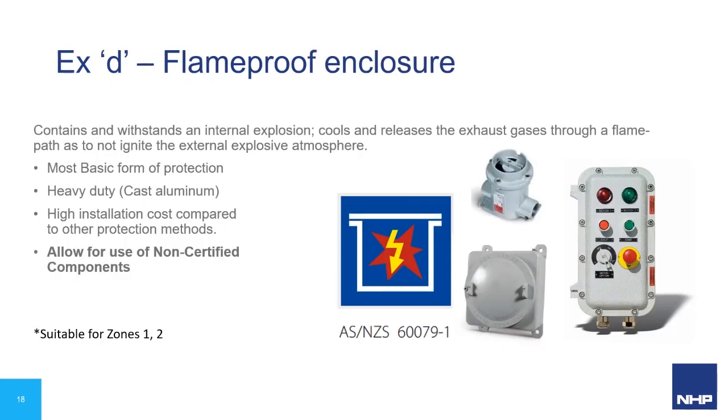Now, EXD is a flameproof enclosure, so you don't want to confuse this with fire-rated enclosures, as they are two completely different things. A flameproof enclosure is allowed to breathe, which means that the flammable mixture is able to penetrate and get in. If an explosion occurs inside the enclosure, it will prevent the explosion from getting out and igniting the surrounding atmosphere. It does this by allowing the hot gases to escape out the sides through special flame paths, which are engraved along the threads and flanges of the product, and act to cool the gas down to below the ignition temperature using the material of the product to do this.